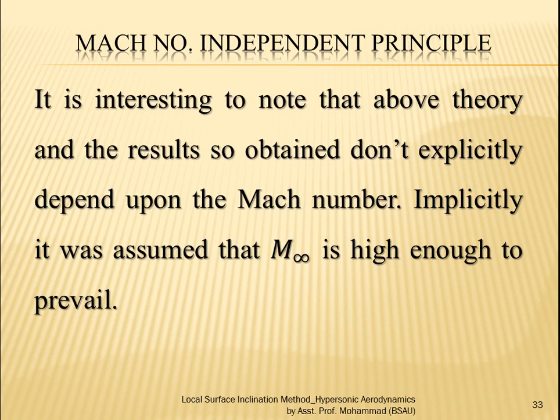Now there is another theorem coming here. We saw very easily that in the high speed regime, the hypersonic regime, the Cp becomes independent of the Mach number. This is a very interesting fact, that the Mach number stops affecting these parameters. In principle we call it the Mach number independence principle. Students should remember this statement by heart, word by word. Hardly 3 to 4 sentences are there. I'm just reading it.